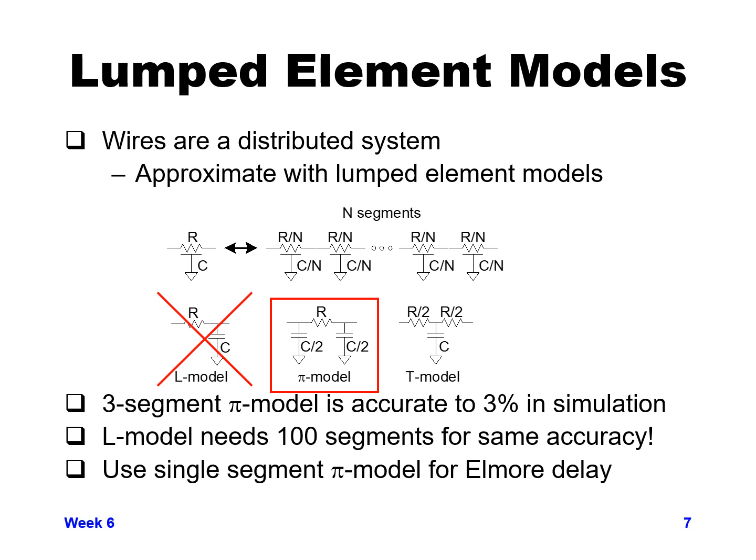But that gets really, really complicated to simulate a wire that has 1,000 segments. It would take a lot more simulator time. So typically we try to make a more simplified model, and a couple possible examples of simplified models would be using either an L model, where you have an R in series with a capacitor at the end, or a pi model, where you have half of your capacitance per unit length on either side of a resistance, or a T model, where you have half of your resistance on either side of a lumped capacitance in the middle.